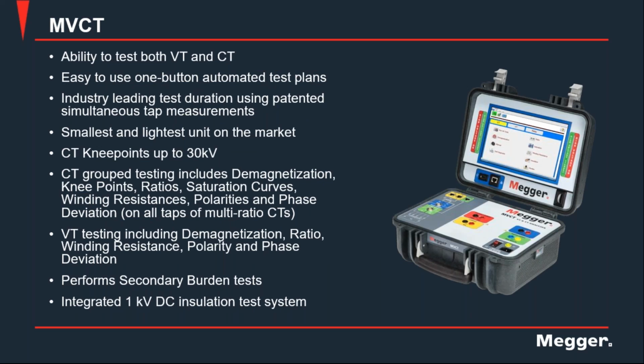And the MVCT is a lighter instrument that uses a different technique for the saturation. There are some CTs that will saturate, will have that knee point at 30 kilovolts or 15 kilovolts, and then you will need higher voltages to test that. Or you can use an alternate method to saturate. Instead of applying AC voltage, you apply AC current and measure the saturation through that system. We have presentations that talk about that method.